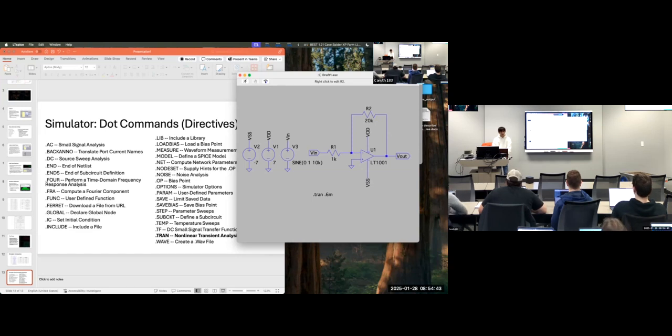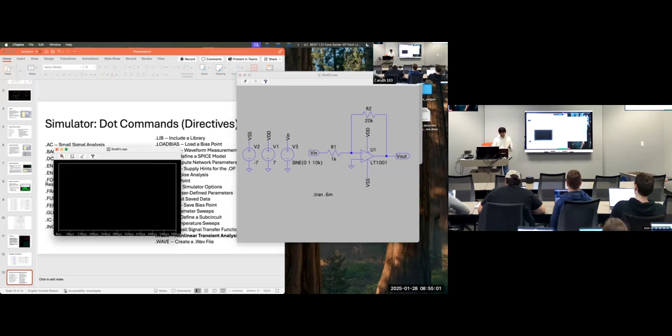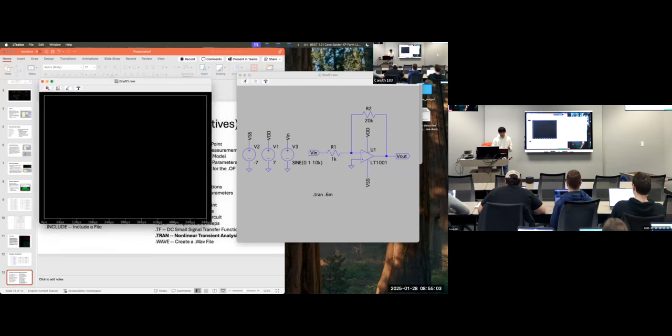Why not? It's going to clip. So why is it going to clip? Because we only have the voltages set at plus and minus 7. Exactly, so we have a peak to peak voltage of 14 volts. So when we put in a gain of 20, it's going to theoretically clip. I say theoretically because this is mathematical software. It doesn't do actual physical stuff.